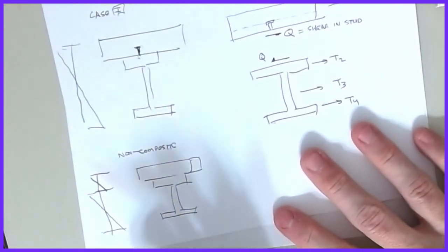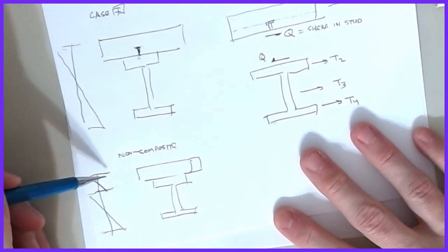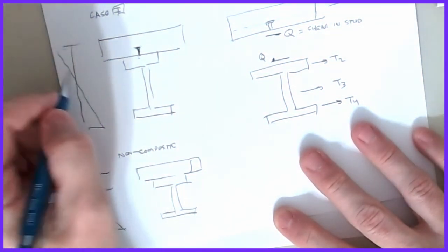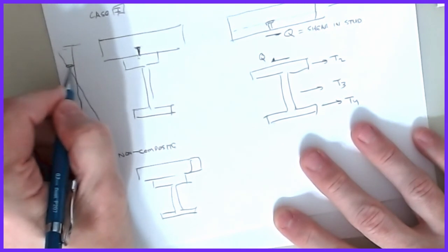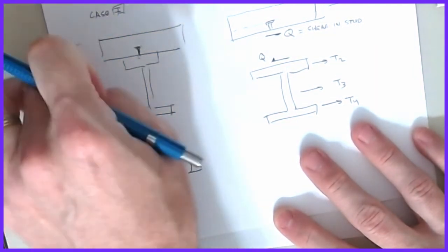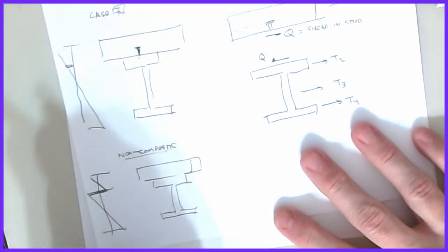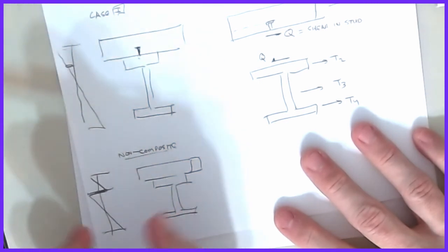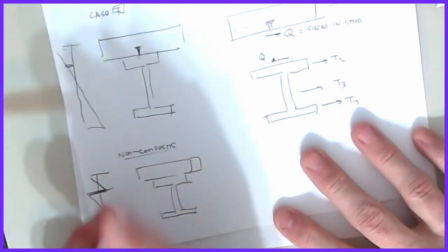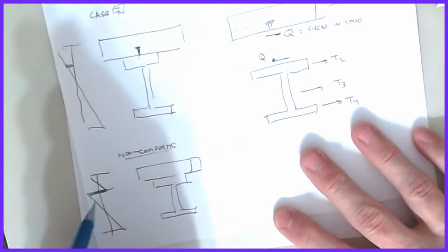And that becomes your strain diagram, and it basically becomes broken on this. So what the studs are doing is, if you look at this line right here, at the same location it was here, the studs are forcing this thing to go back in to form this guy. Right? So that's the difference. Depending on how many studs I give, the more studs I put in, the more I start to squeeze this line in, and if I put enough studs in, I can get back to here, but that becomes the strain case.